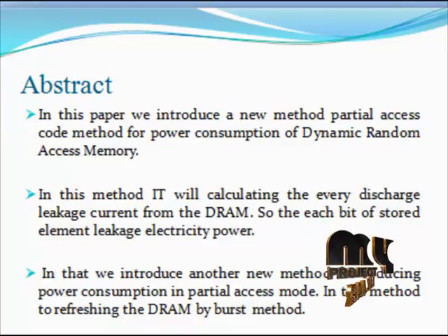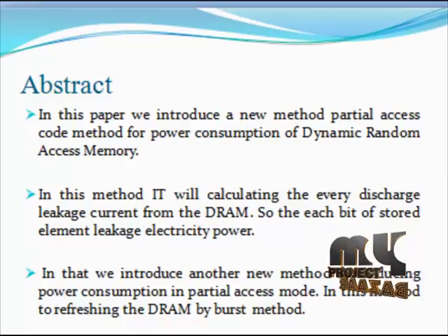Although active power increases by a factor of 2 power n, the refresh operation time increases by more than 2 power n, as a consequence of the fact that majority decision does better than averaging on the tail distribution of retention time. The conversion can be realized very simply from the structure of the DRAM array circuit, and it reduces the refresh power consumption by 2 orders of magnitude.